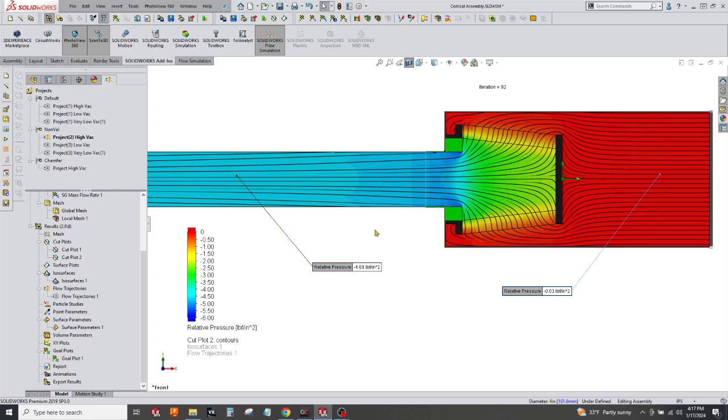So that's going to drive this flow. Now, for what it's worth, and any of you who understand this, 4.5 psi is a pretty substantial amount of vacuum, probably something that would only be induced with a big power adder, probably like a turbocharger or a supercharger or something like that that can really generate a lot of flow.